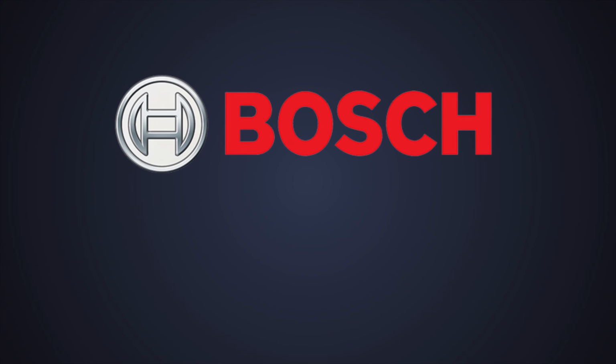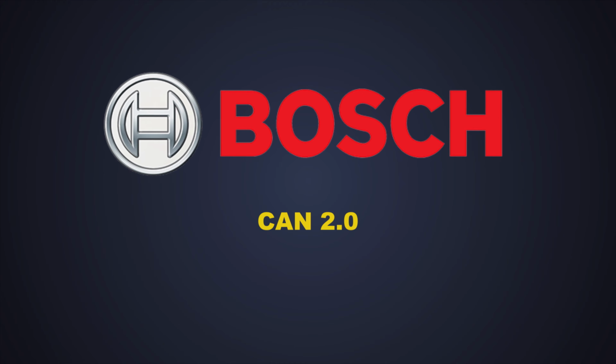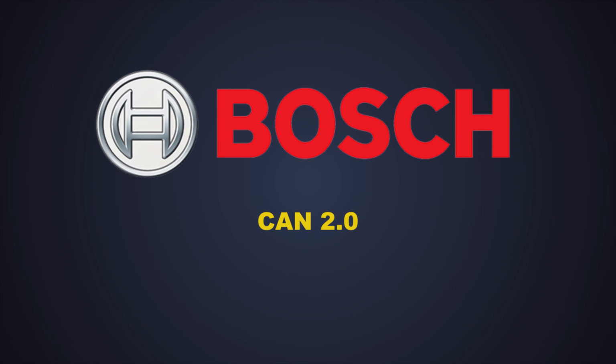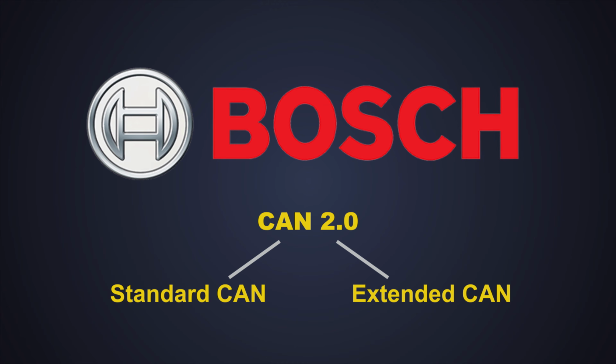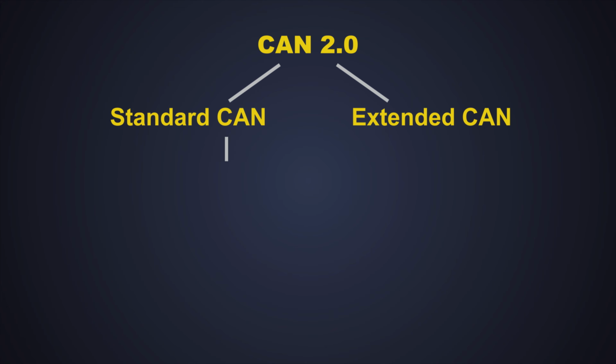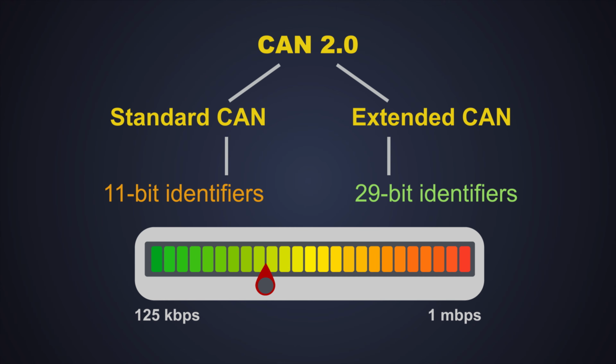Bosch has come up with the CAN standard version 2.0 specification. This specification is further divided into two subdivisions, that is, standard CAN and extended CAN frame. The standard CAN frame comes with 11-bit identifiers and it signals at a rate of 125 kbps to 1 Mbps, whereas the extended CAN has 29-bit identifiers.